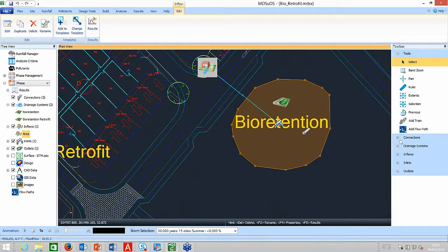Okay, so we have the areas of runoff, you have the runoff entering into the structure. We could connect structures together. We can put in inlets. I mentioned the inlet being an important aspect nowadays. And if we put in a swale, for example, or that bioretention area down the highway, we can then model the lateral inflow entering into the structure.